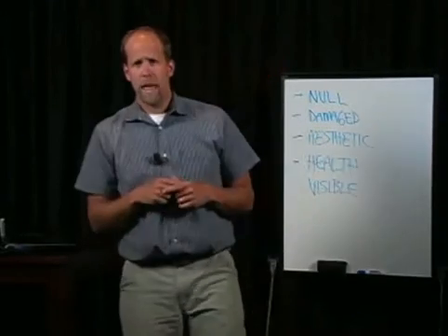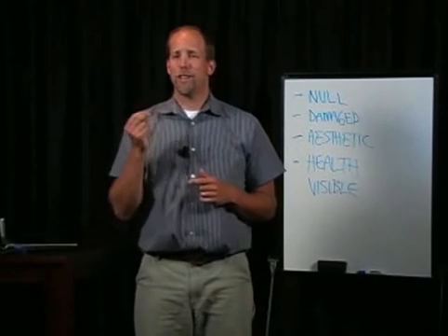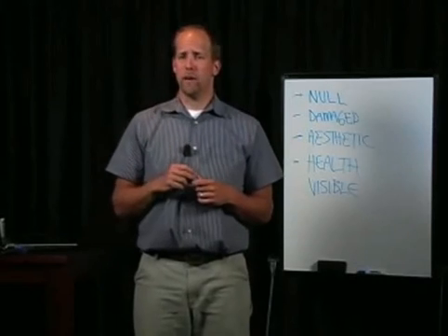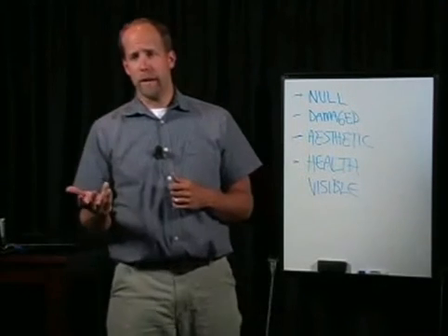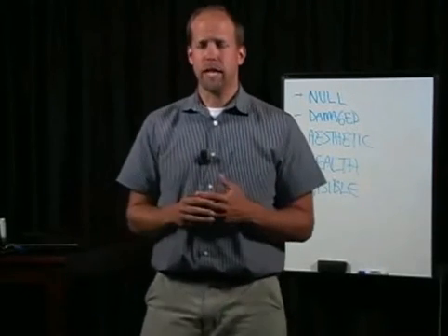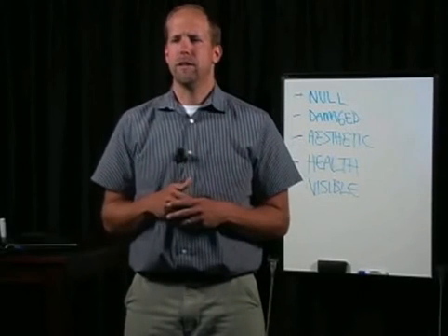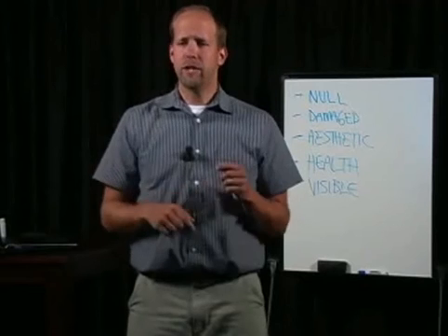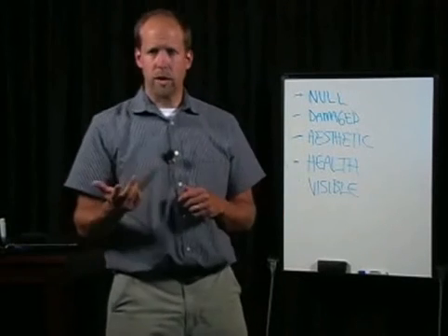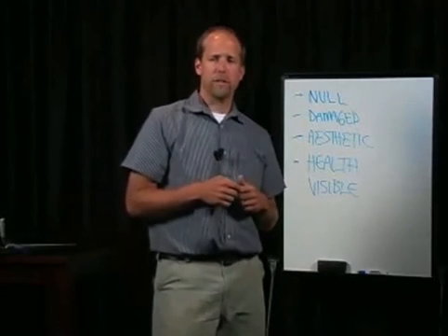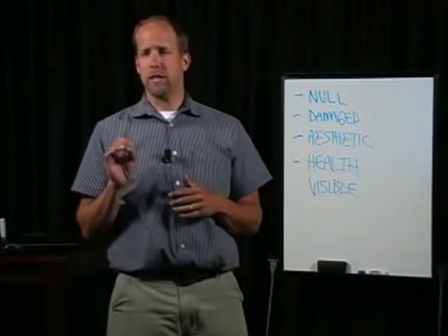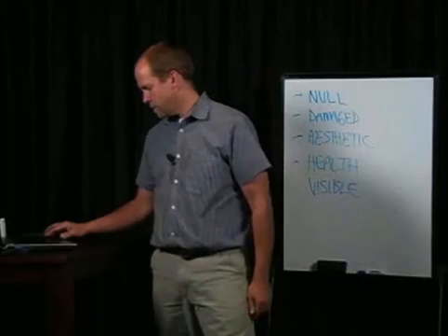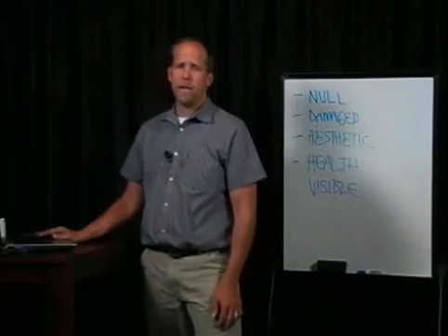Number 2, ask for the proper spelling of your client's name, their current address, and contact phone number and email address. Ask for the property address where the inspection will be performed. Set a date and time of the inspection. Request that the client attend the inspection. Get information about gaining access to the property, including the owner's name and contact information, and confirm the type of mold inspection that is being ordered by your client and the fee for the inspection. Number 3, prepare.